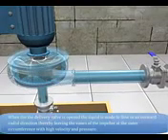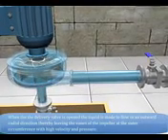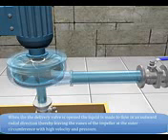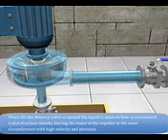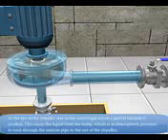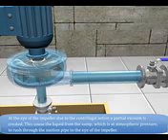When the delivery valve is opened, the liquid is made to flow in an outward radial direction, thereby leaving the vanes of the impeller at the outer circumference with high velocity and pressure. At the eye of the impeller, due to the centrifugal action, a partial vacuum is created.